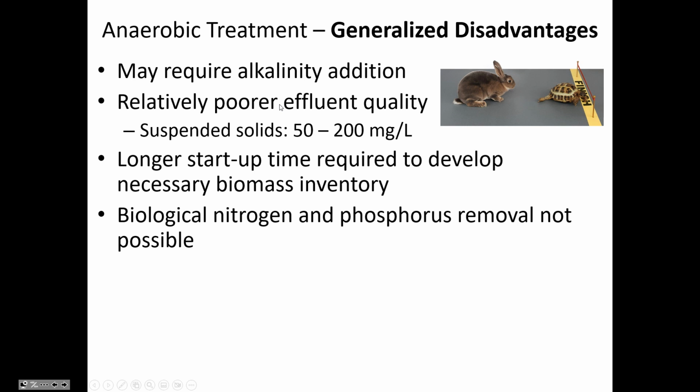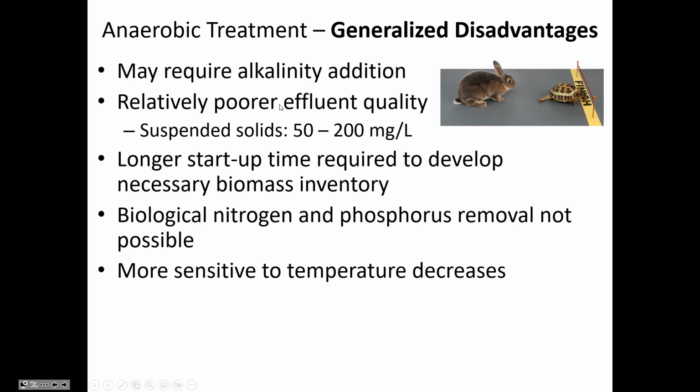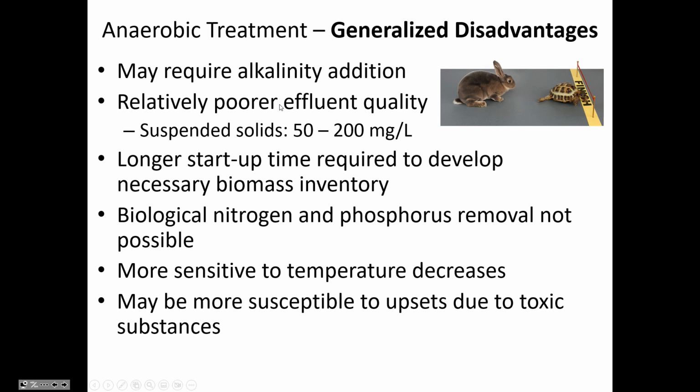Nutrient removal isn't possible in traditional systems. There have to be other steps along the way to have the removal of nutrients. It can't be done just in a single stage, and it's very sensitive to temperature changes, and if toxic materials come through, the microorganisms that live in an anaerobic environment are very sensitive to those, and like it said in the earlier bullet point, the startup time, if you do have a kill of all the microorganisms, is very lengthy.